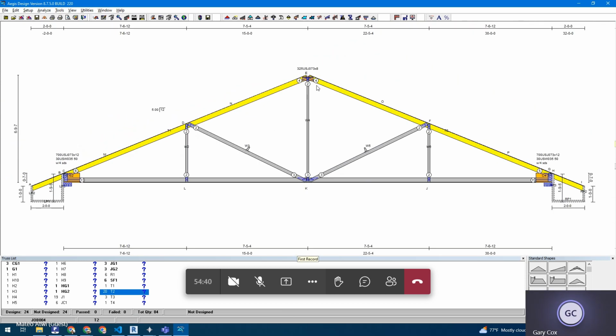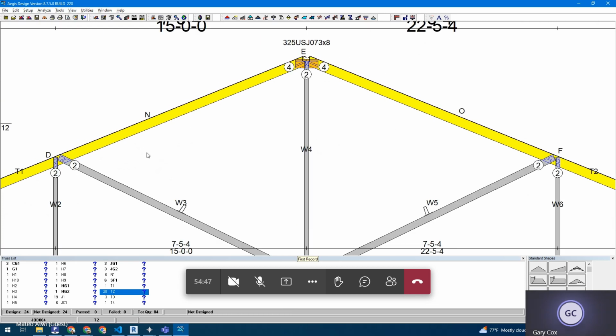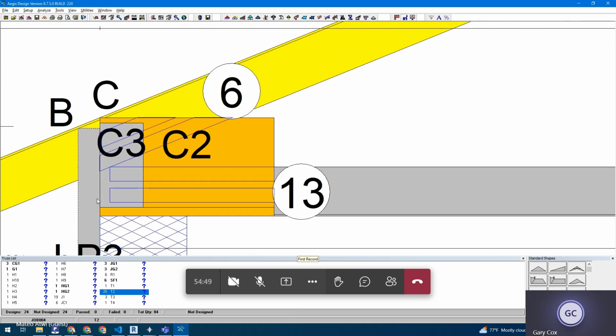It gives you a visual because that's where it bends towards the back end and comes back. There are two flat areas that you can put screws in. You don't want to screw right in that middle area because the screws won't be long enough. So it gives you, the designer, a way to see it.